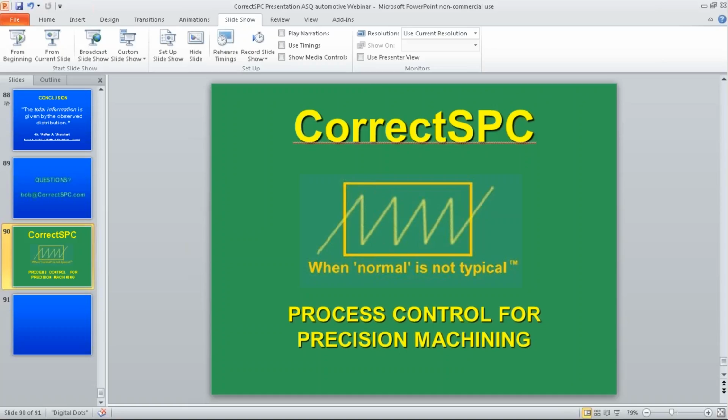You can't be looking at different areas, because that'd be no different than if you were measuring a circular feature in different areas and being masked by taper. You don't want to do that. You want to measure in the same location all the time. And you'd have the same issue there. You have to measure the same location, and you should be able to see over a long period of time that tool wear, and it should be predicting when to pull that die out when it's hit the end of its life and due for change, if you don't have other things such as edge condition that precedes that.